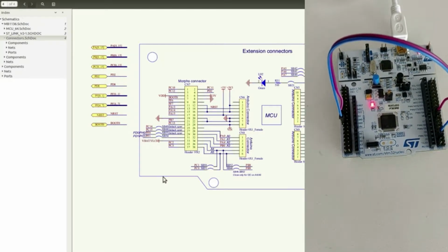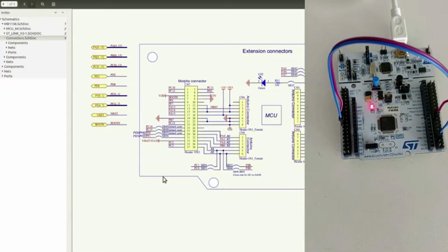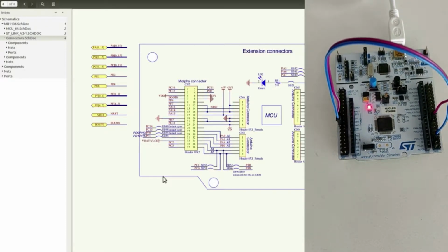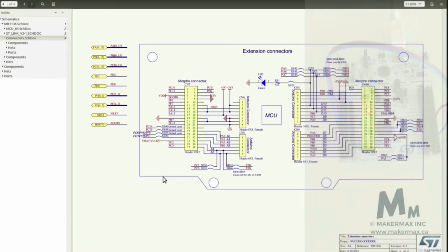These will let you connect, externally on the board using wires, I2C peripheral 1 and peripheral 2. As you know, I2C has two lines, the clock line and the data line, so you would have to connect using two hookup wires. You would have to connect SDA and SCL of the first peripheral to the second. That's it. You need one line for connecting the SDAs together and the other line for connecting the SCLs together. That is all that we need.